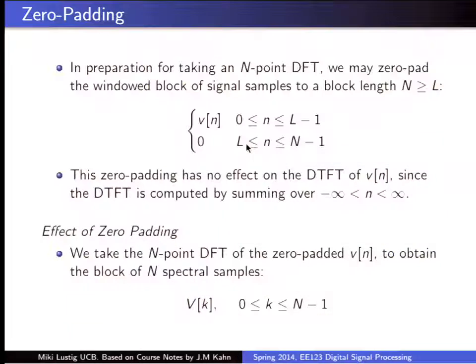Oh boy! All right. So, what is really zero padding? If I have an infinite sequence and I just take a window, I multiply by a window, right? And I basically compute the DTFT. The DTFT I compute over an infinite sequence, but most of it is 0. So even for the DTFT, I only use that window in order to compute it, right?